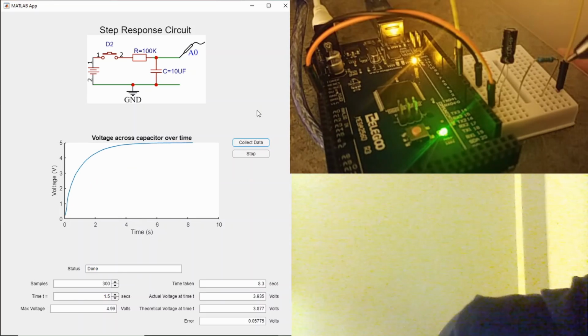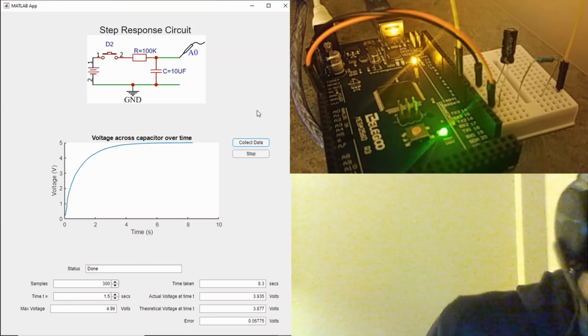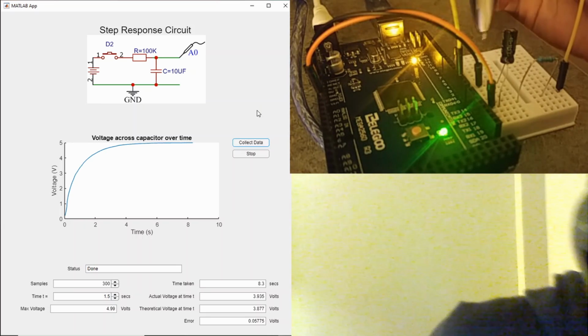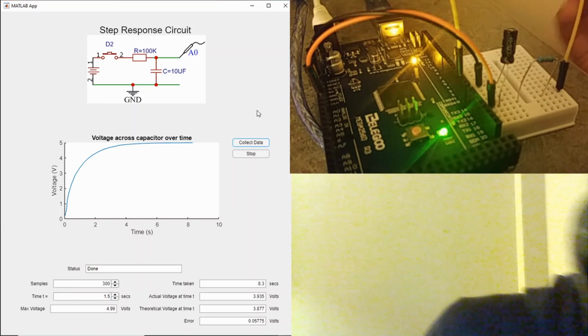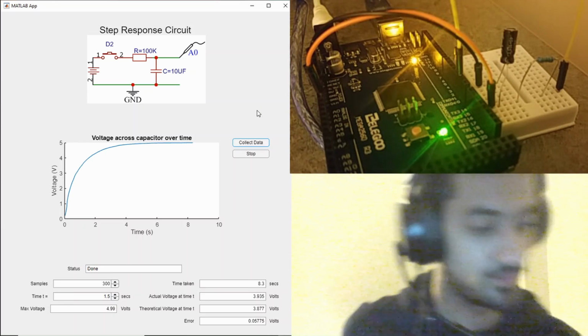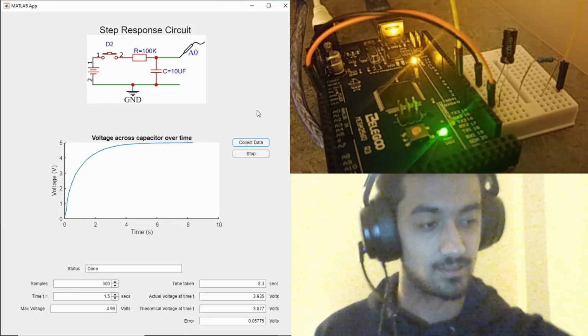So here I have my resistor, which is connected in series to my capacitor. Here I have my yellow wire, which is the output of my Arduino, which acts as an input voltage into this circuit on my breadboard. Here I have my orange wire, which measures my voltage across my capacitor into pin A0. And finally, I have my black wire, which acts as the common ground wire between my Arduino and the left side of my small breadboard. Finally, I made sure to connect my capacitor the correct direction so it doesn't pop out and release noxious gases into my apartment. So that being said, my circuit correctly matches the schematic.